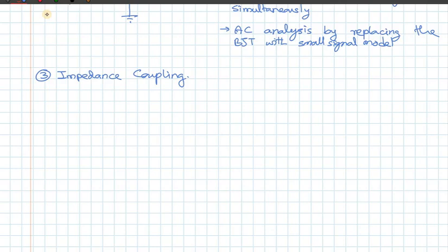The reason for this is most of the circuits we had RC, okay, and the resistor in the collector circuit, across which we had a large power dissipation, I squared R, IC squared RC. This energy, this power was not useful because our load was separately connected, the RL. So the RC, the power across this was a waste. There is no usefulness for this voltage, this power across RC, unless RC itself is the load.